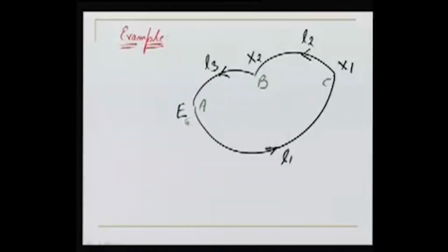One more way is possible. I can straight away go from A to B as well as from A to C. So what we are seeing here, we are doing the same thing. We have done this over here. From A, we found L1. L1 is the difference between RL of A and C. Using that, we can find the value of X1. X1 is the RL of C.